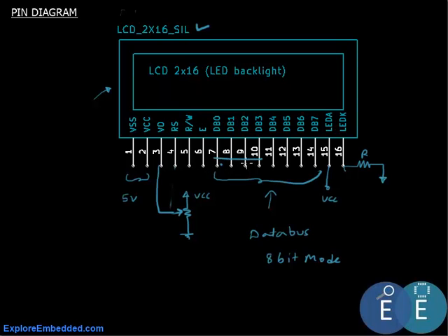And a point to remember here is, whenever we're using just 4 bits or in 4-bit mode, only the higher 4 bits DB4 to DB7 are active. So we cannot use 4-bit mode from DB0 to DB3. Whenever you're using 4-bit mode, it should be pins DB4 to DB7. So this can also be operated in a 4-bit mode.